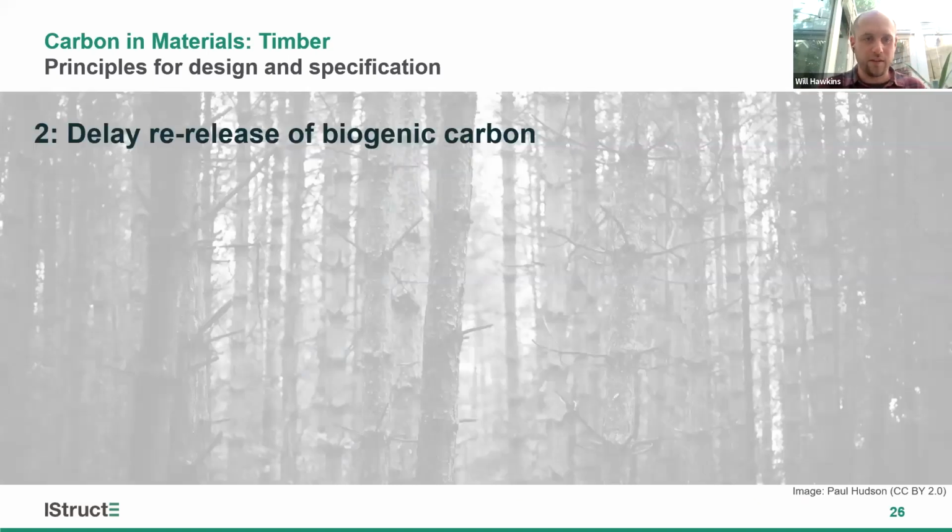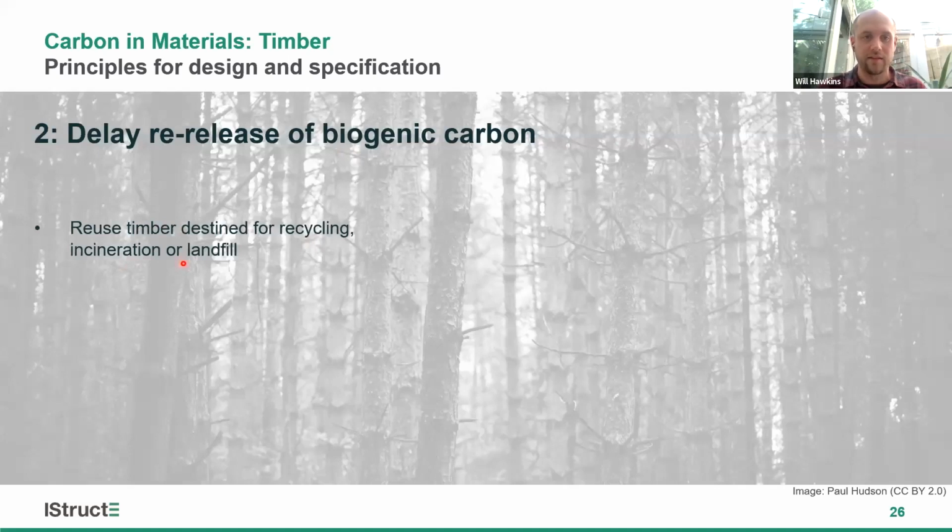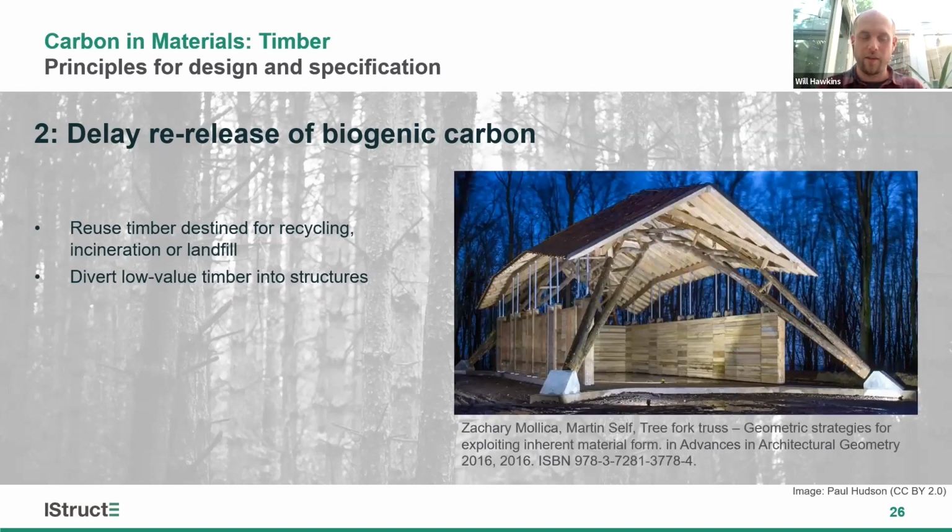The second key principle is to delay the re-release of biogenic carbon. You can do that in a number of ways. Firstly, by reusing timber destined for recycling, incineration, or landfill. That might be some local floorboards that you can get hold of, or it might be a whole existing timber structure. You could divert low-value timber into structures. So this is an example from Hook Park, where they've taken small diameter roundwood and built a fantastic structure out of it. That timber would have likely otherwise been burnt. You should always maximize the lifespan and design your timber structures to last a long time, and design components so that they can be reused in future.